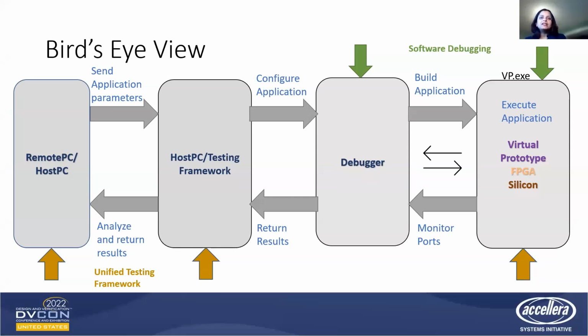So that way, anybody can debug both the application code and the virtual prototype source code together. Now, this is a very positive aspect of virtual prototyping and an extremely powerful debugging feature. For hardware-software debug in a virtual prototype, as compared to silicon or FPGA, there is much more visibility. We used Visual Studio to build the executable, hence it was very easy for the software folks to navigate and debug. This entire system proved to be very helpful in the early development of the software testing framework itself.